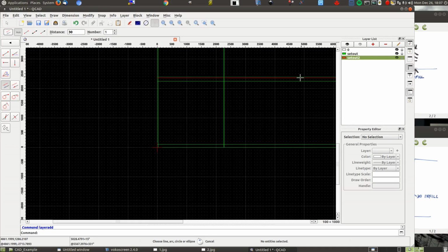Right. Now on set out layer 2, we'll draw the thickness of the board in. Now it's important, I actually don't know how well to stress this point. So many people bring me drawings as a cabinet maker, and they sketch what they want, and they just draw any uprights as a single line. Meanwhile, everyone's left confused as to which side of the line a dimension is referring to. It's important to always include the thicknesses of your materials when you're drawing things. If you don't include those thicknesses, things get out of control pretty easily. So okay, now I've done my little preach.